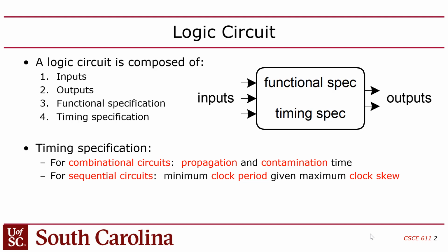The data path is when you have a memory element, a flip-flop output that goes through combinational logic and then goes to the input of another flip-flop, right? That's a data path, right? Your CPU operates in terms of data path operations. The worst case timing, the worst case delay for a data path has to be 20 nanoseconds, right?